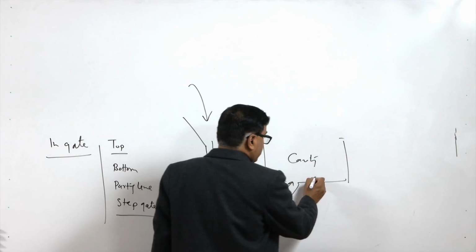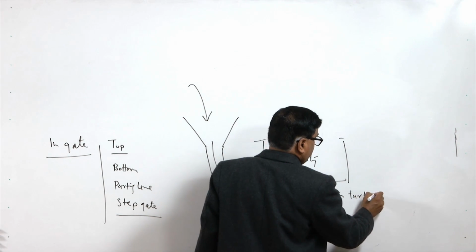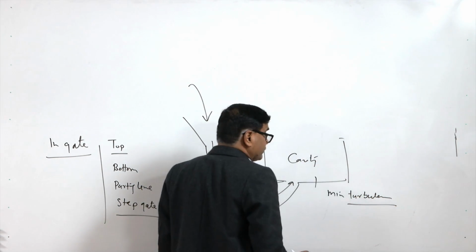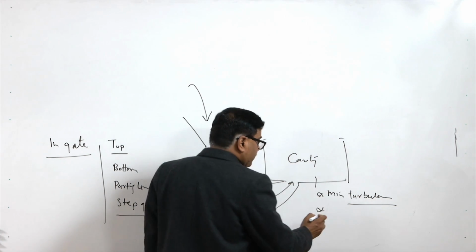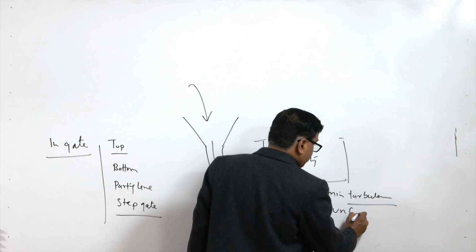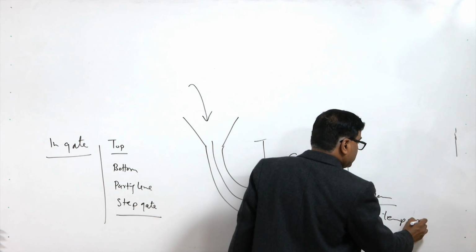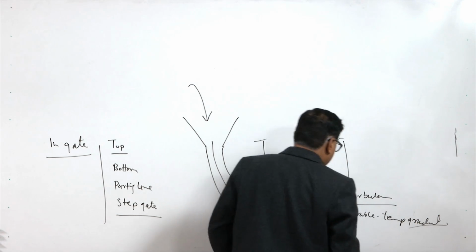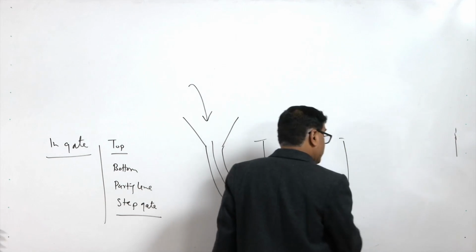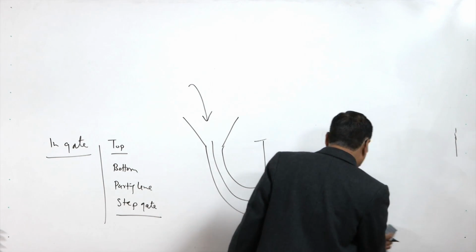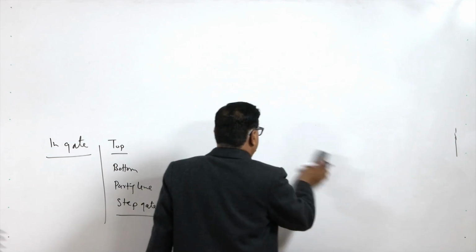So, in this case the molten metal enters from the bottom side of the cavity. The good part is there is minimum disturbance or turbulence to the molten metal, and there is no erosion. But the only problem is that it leads to an unfavorable temperature gradient. In this case it is difficult to realize directional solidification, and it may lead to internal defects like shrinkage cavity in the mold.